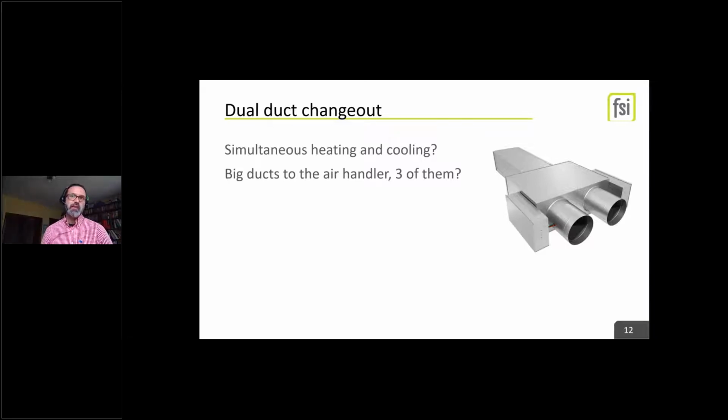And so in the code now, there is a solid provision. You can't simultaneously heat and cool, except with some extremely limited provisions built around variable air volume systems where you slightly overcool and slightly reheat, but have to do temperature reset and a bunch of stuff.